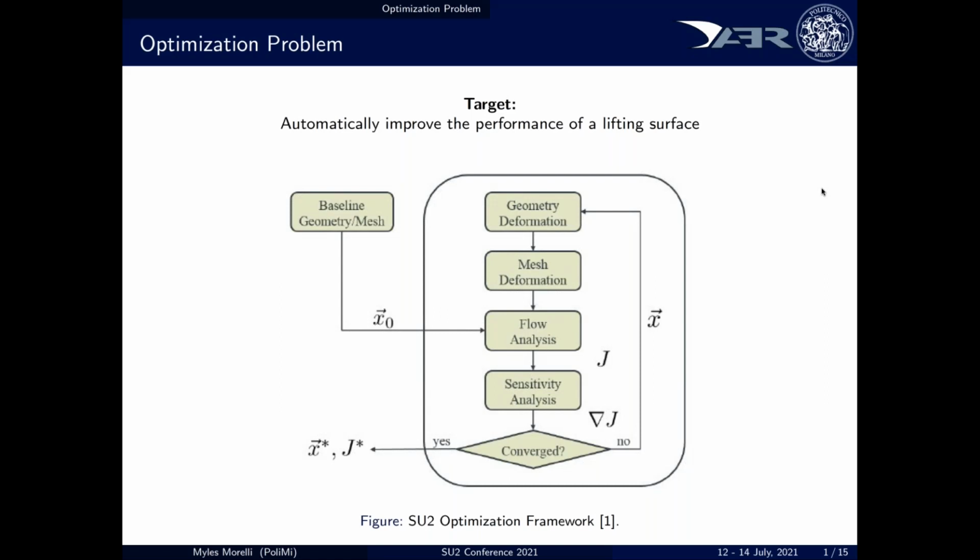So we start from a solid that we want to modify. We select an objective function that we want to reduce, usually the CD coefficient. We use a technique called freeform deformation for describing the body mathematically, and the vertices of the box where we introduce the body are our design variables. We use the discrete adjoint to compute the surface sensitivity. In SU2, for the discrete adjoint, we use a technique called AD, automatic differentiation, which differentiates also the routine for deforming the mesh. So the surface sensitivity is going to change if we change the method used for deforming the mesh. So the method of updating the grid is essential for the final result.